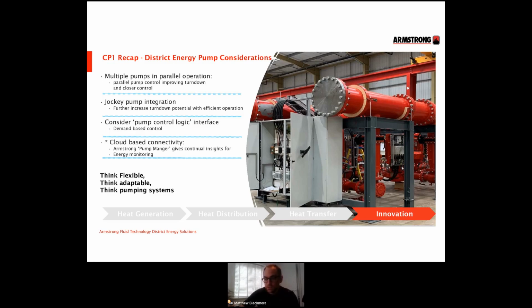We refer to this at Armstrong as a jockey pump, and this mitigates the poor turn down and controls at low levels. So correct selection and system integration, however, generally at this level is poorly executed. There is a lack of understanding on how to actually make that changeover happen. Control logic: CP1 recommends enlisting a pump manufacturer's recommendations, something that unfortunately still doesn't really happen very often today.